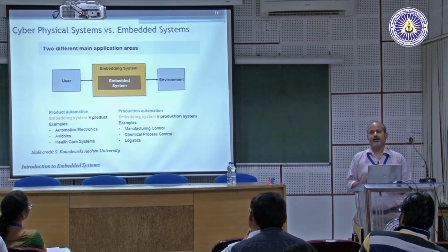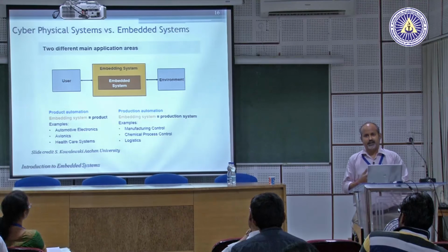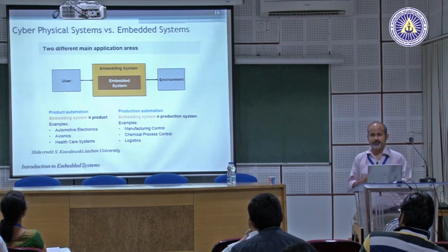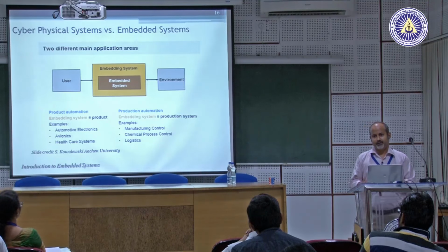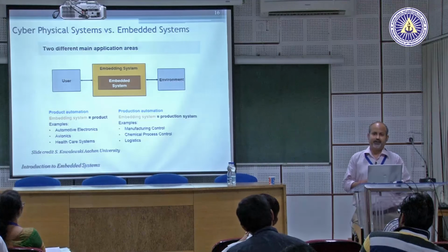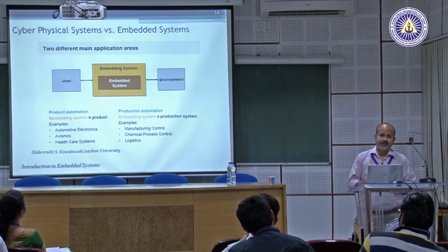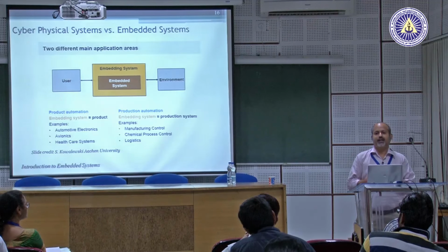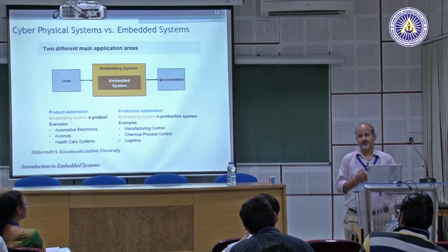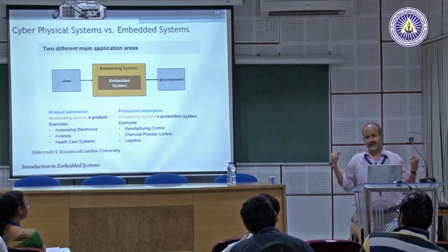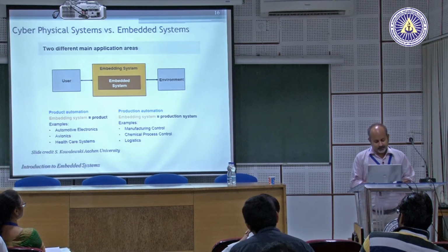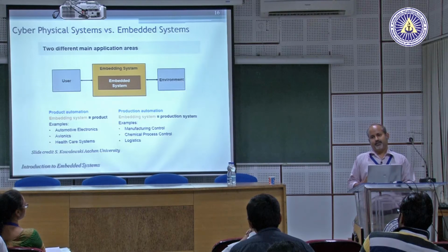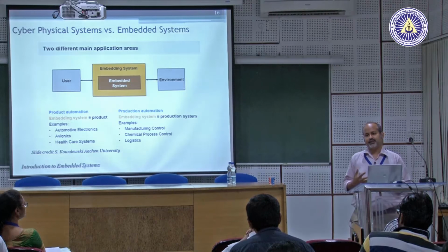They are going to go into certain substations, and in the substations they are going to be stepped down or stepped up depending on what you are doing, and then moved into various directions. And then eventually these transmission lines will come to a distribution substation, and then from the distribution substation you will have distribution lines to various localities and so on, right? So in this kind of a system, there are multiple different problems, right?